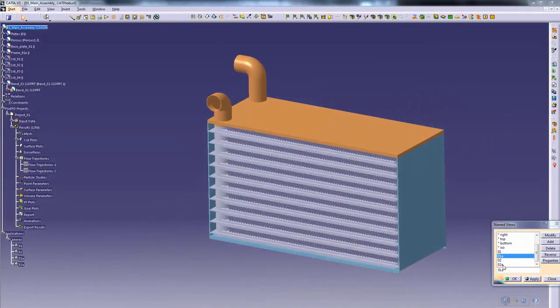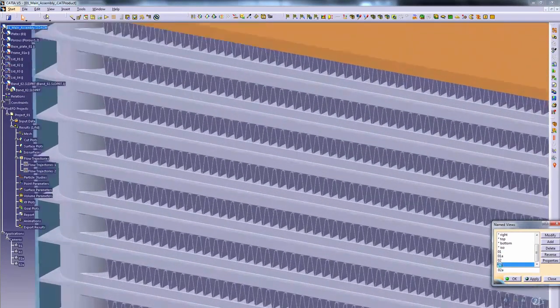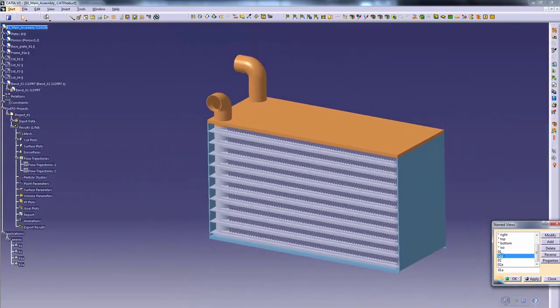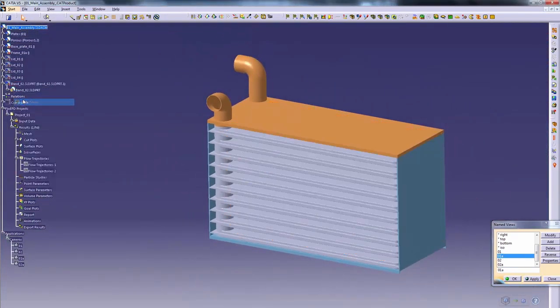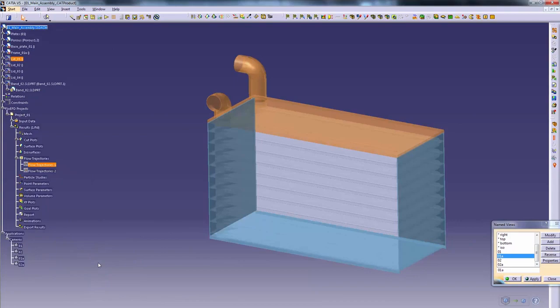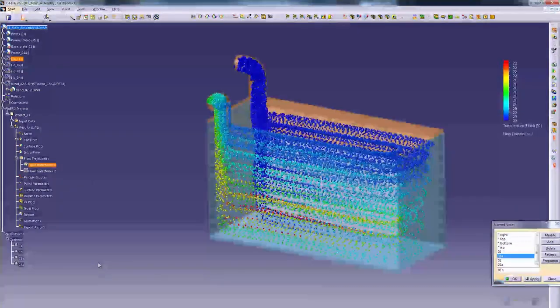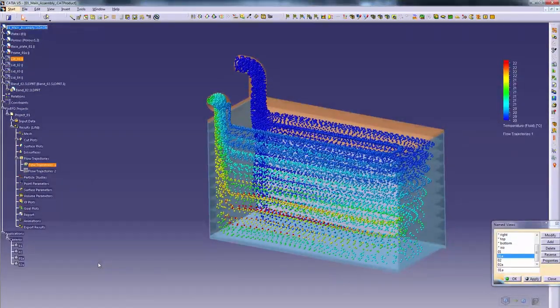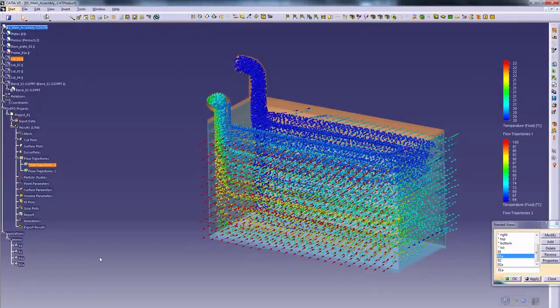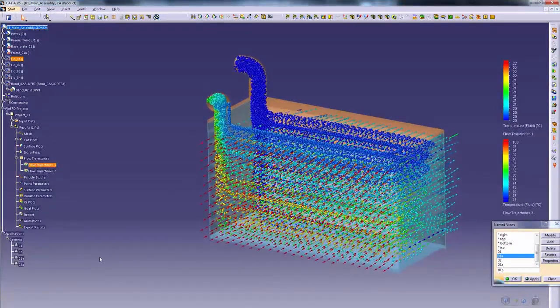This is a representative example. To increase the heat exchange area, plate fins are arranged in the air side. We will use the porous media capability as a surrogate material because a detailed simulation of these thin structures would result in an extensive calculation time. The inside flow medium is water. The water side has two passes in a U-shape, and the outside medium is air, which is cooled down in this example by the cold water.